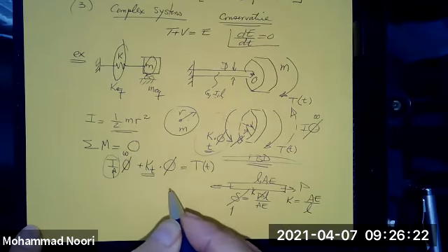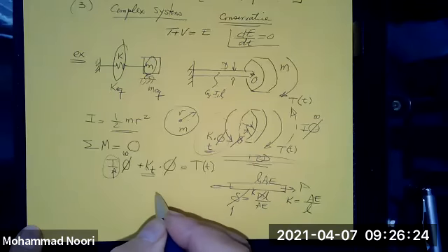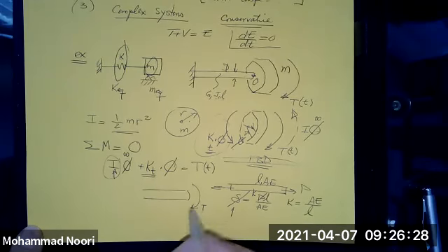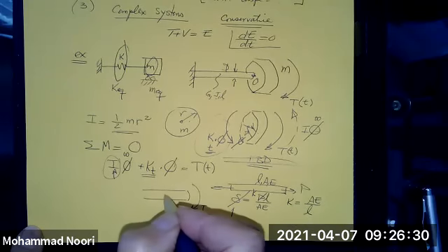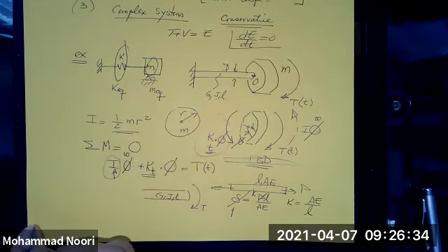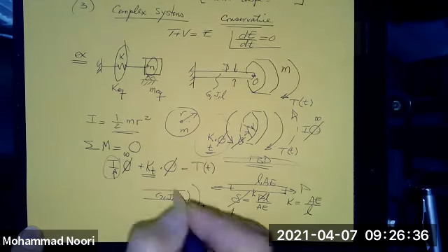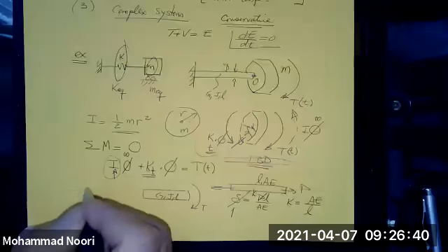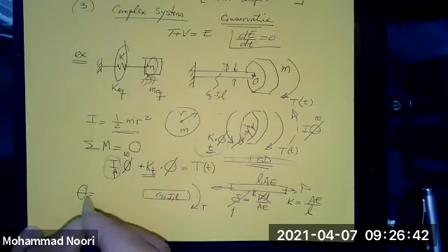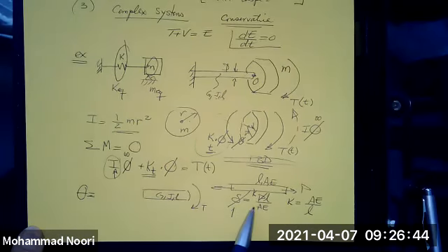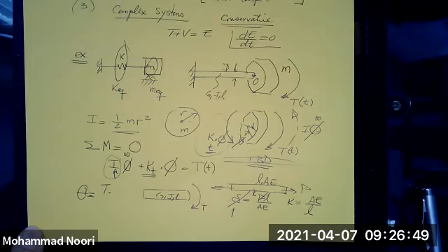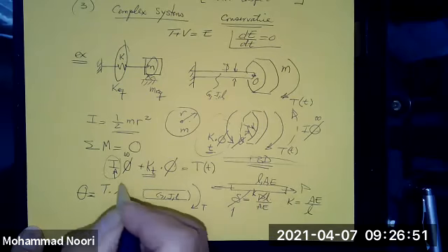How about for a shaft that is subjected to a load like this, and these are the parameters that we have. If this shaft is experiencing a deformation theta, if you don't remember the formula, use an analogy here. For P, you put instead the torque. L is the same.